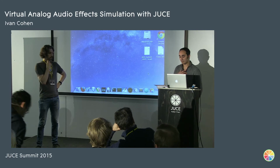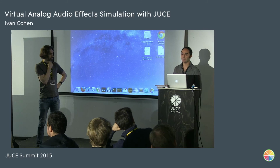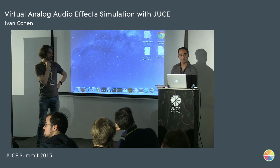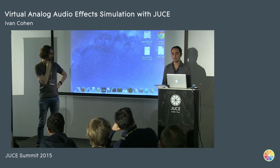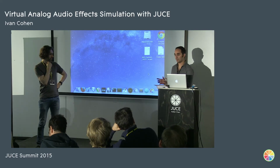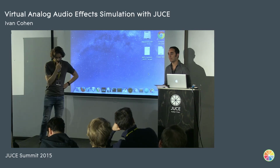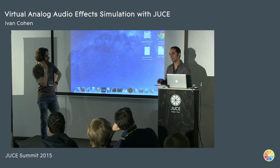So about myself, I did a PhD thesis about guitar amp simulation in the past. And obviously, there is a lot of things going on in guitar amp in general. And the first thing we do to be able to have something in real time is to divide all the sections in the guitar amplifier in blocks. And we simulate each block separately of the others. And then we are using some techniques to model the coupling between these blocks.